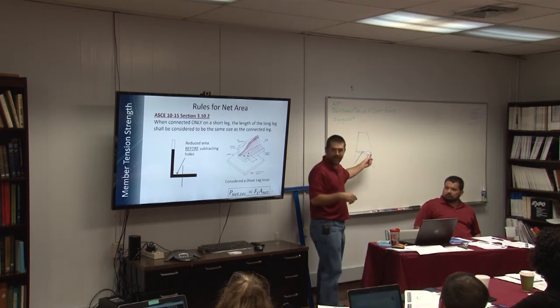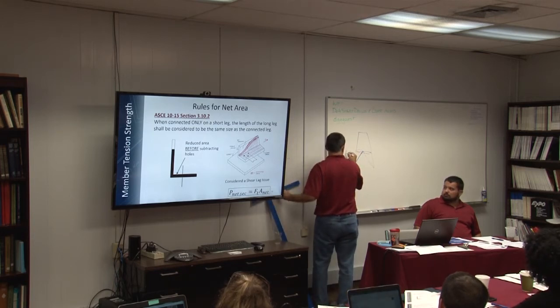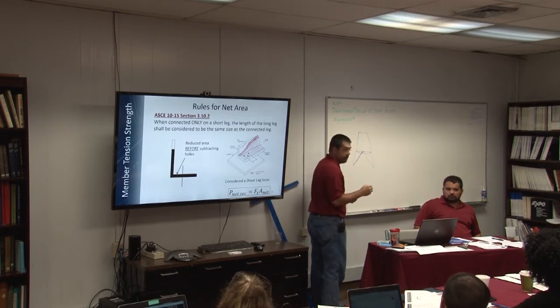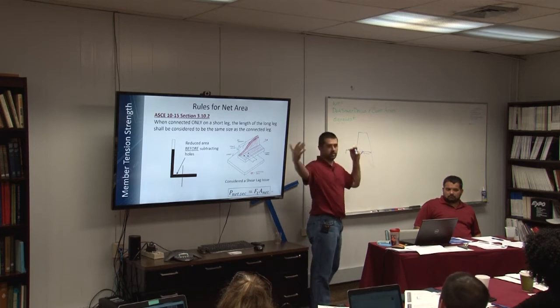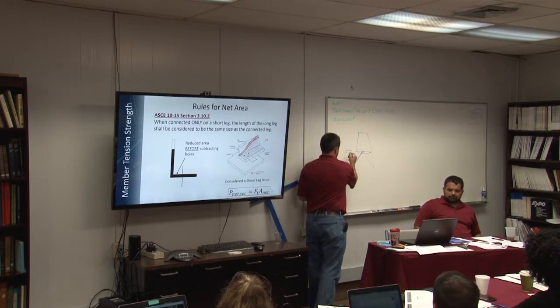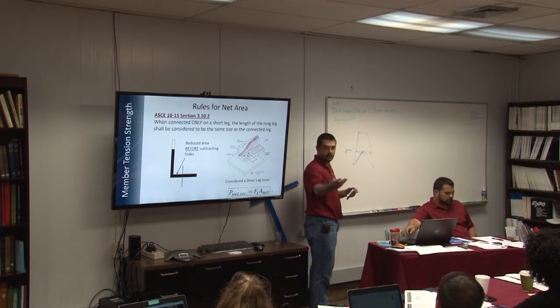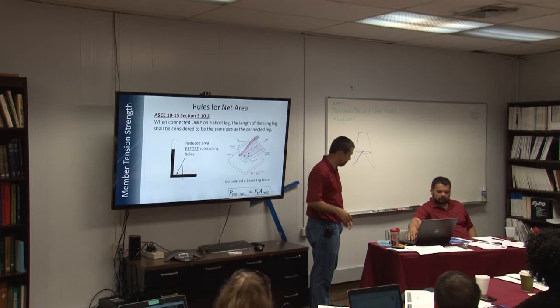So if I have an unequal leg angle and I orient it such that the long leg is basically horizontal, then I'm putting the stronger bending axis in the direction of the longer unbraced length, so it can create a more balanced design. And so that's a situation where it's going to be connected on the short leg. So when you're looking at a net section, you're going to have to look at it with the reduction, but there's benefits in buckling.